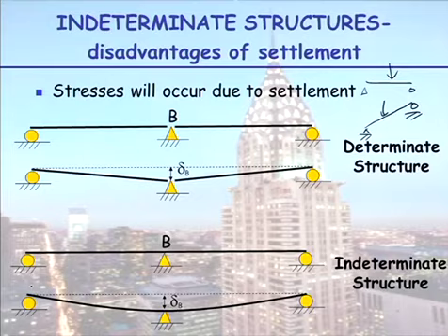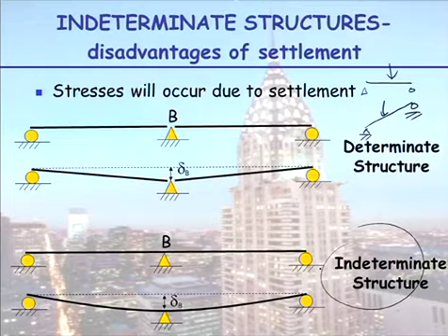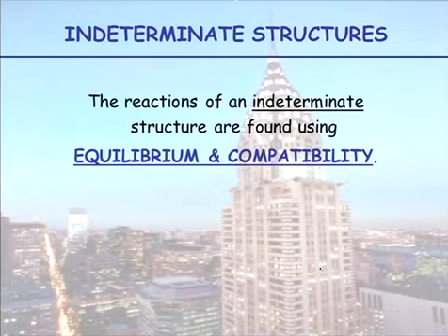So you would have to assess what's more worthwhile, or you would just say, okay, well, I just have to take into account. And quite often, when you look at structures, as well as dead load, live load, you have temperature loads. You have settlement loads as a load case. So you would consider those as load cases. Okay, our structures are indeterminate, so what do we do?